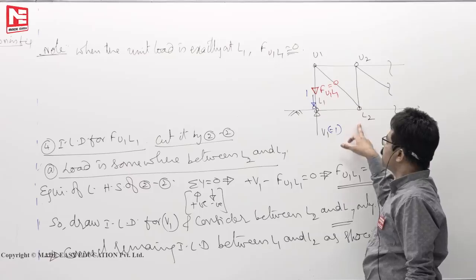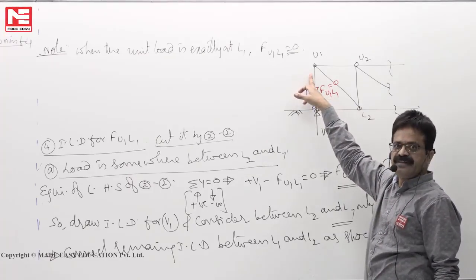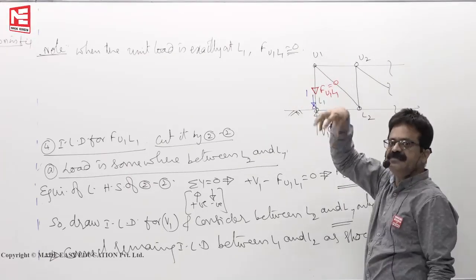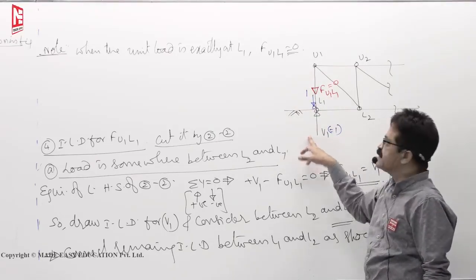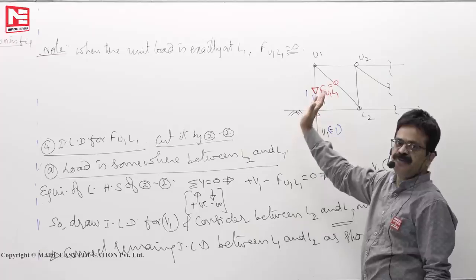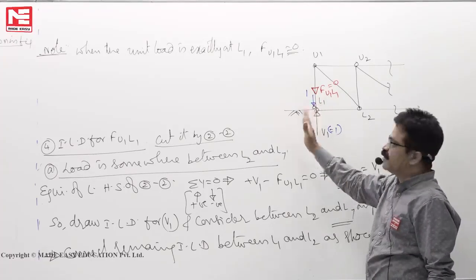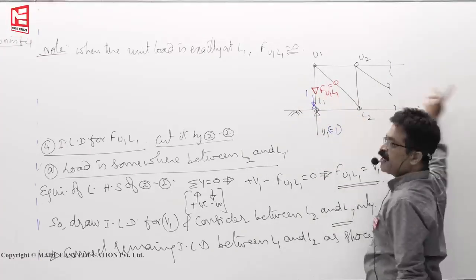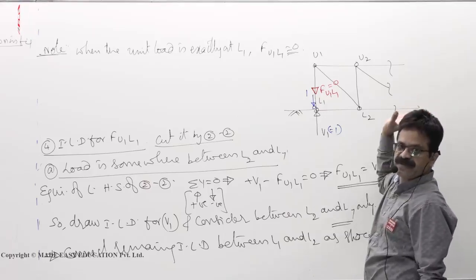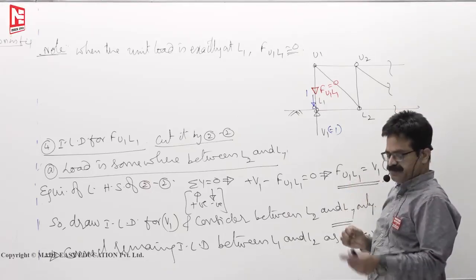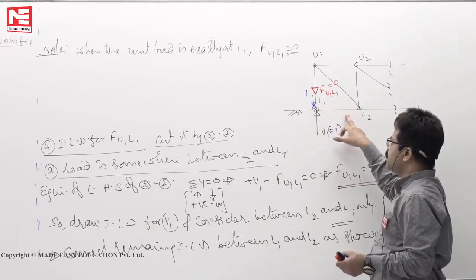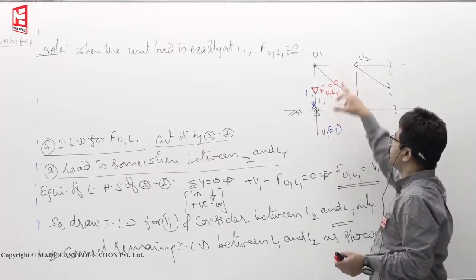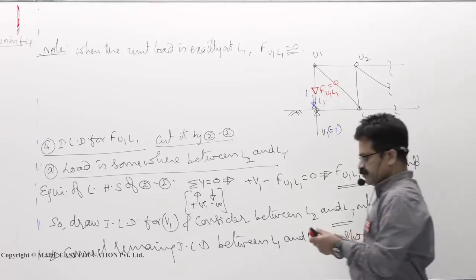Supposing that out of this 0.5, this takes 0.1, that means when load is acting, it takes 0.1 and transfers it. The already existing 0.5 plus this 0.1 together gives an upward reaction of 0.6. Then at the other end 0.4 is transferred, like that. So that is the meaning of that. Once the load crosses the cross girder, only then does the truss start taking the load.